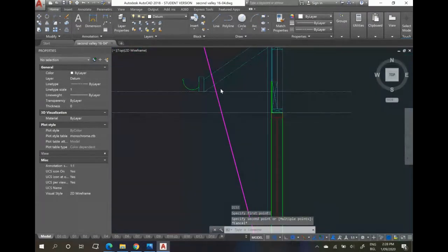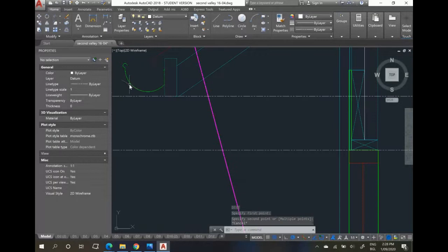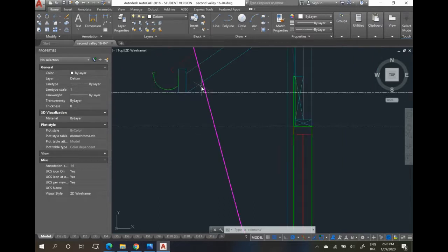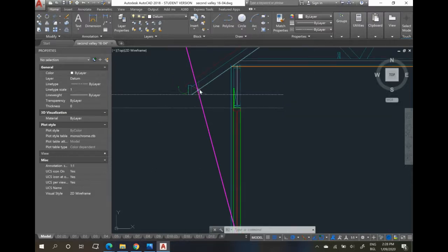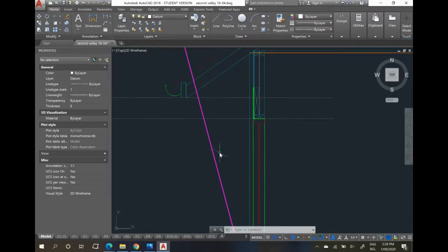You can also get tricky and account for the gutter, etc. For the sake of this exercise, let's just treat our eaves width as that final distance there, without accounting for our gutters and so on. So that's how we get what our eaves width has to be based on our angle at the height of sun for summer solstice, height in the day.